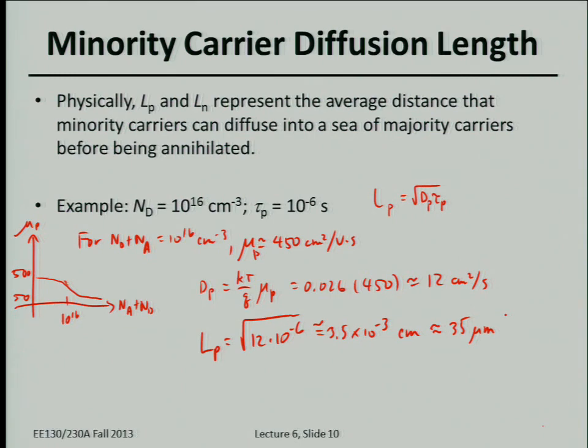Let me just remind you, in a typical metal oxide semiconductor transistor, you have heavily doped source and drain regions, and the current flowing between these regions is controlled by the voltage that you put on the gate electrode. Does anybody know, in the most advanced transistors today, what is the minimum spacing between the source and drain?